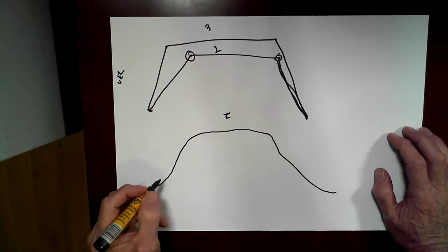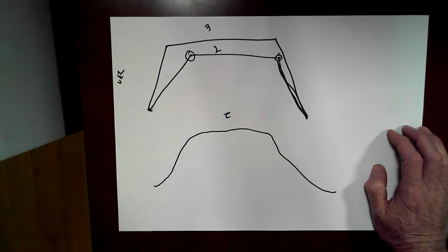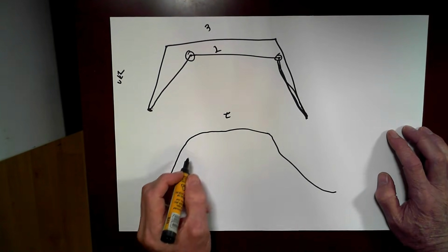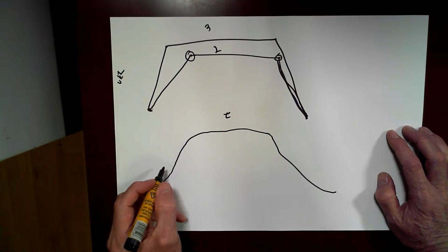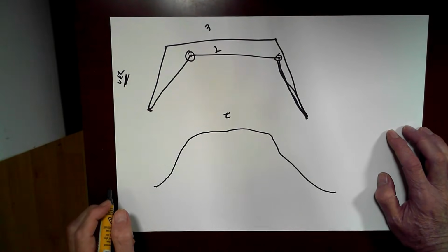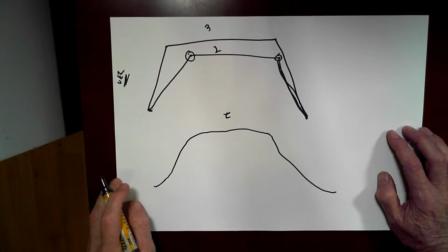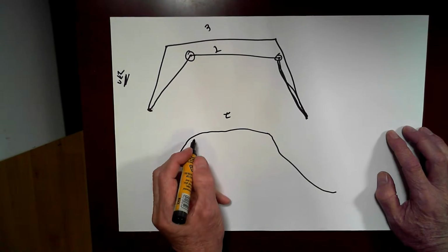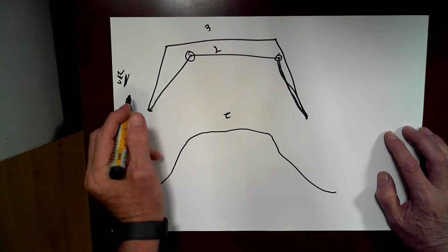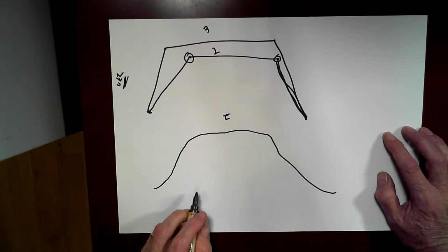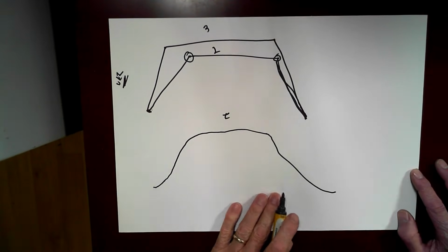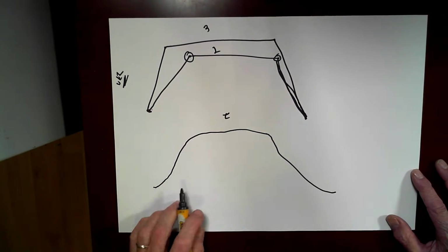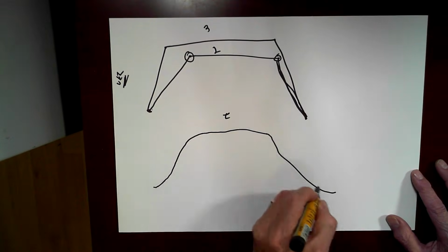And the important thing about this is we've got to make sure that we don't violate where we move up to these speeds. We've set a maximum velocity in the ini file, and that's what's been determined as being what your machine needs. So because we're varying velocities, we need to make sure that we don't violate any of these machine constraints in the operation. So this is the goal. We want to get from this simple trapezoidal motion to a slower curved motion.